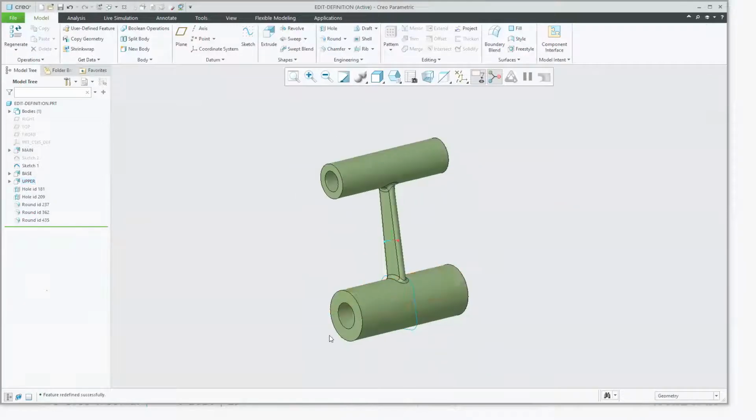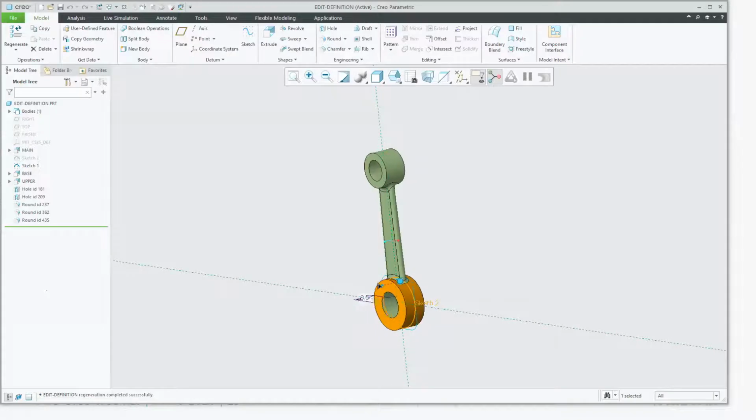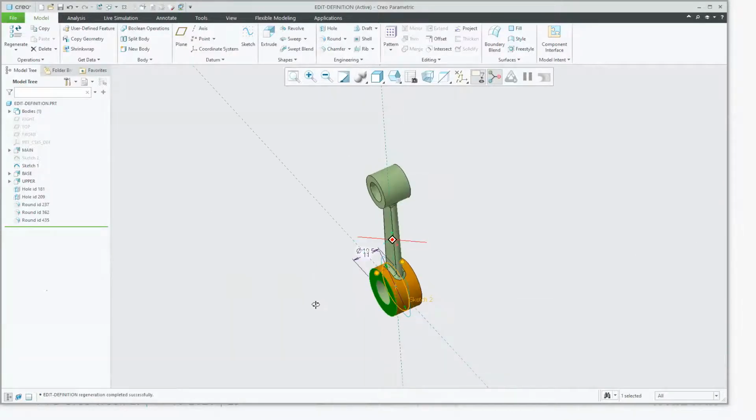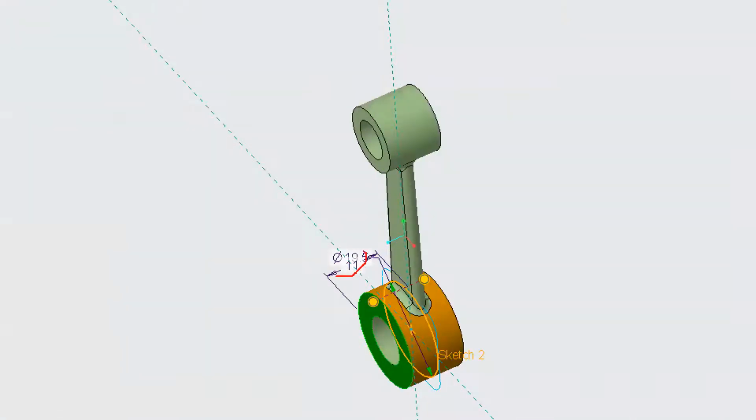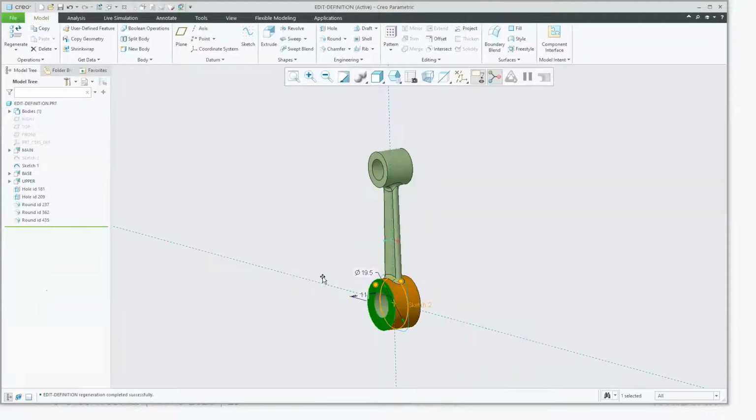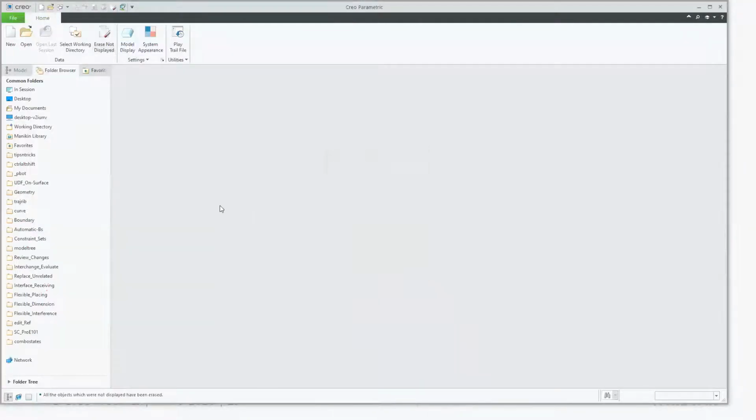So now when I make that change, it's a simple one, most of you know, right? Creo is all about design intent. There it is. When I make that change, it should update. I don't want unnecessarily two dimensions telling 11 and 11. It should be 11 typical in my 2D drawing. If you update that, it should update the other, right? That's the design intent here. Just to show you where that shift could help in Creo, right? Holding down the shift and the controller, different options here.